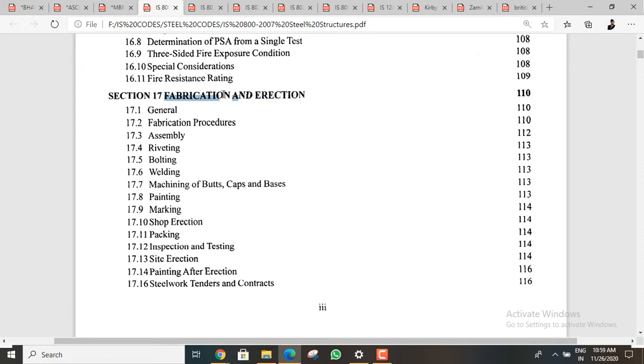But coming to fabrication drawings, whenever we are designing and we have done the detailing, we need to submit it to fabrication by taking this. See, if you have some frame, an I section, in the PEB we will give you the top flange separate, the bottom flange separate, and the web separate.